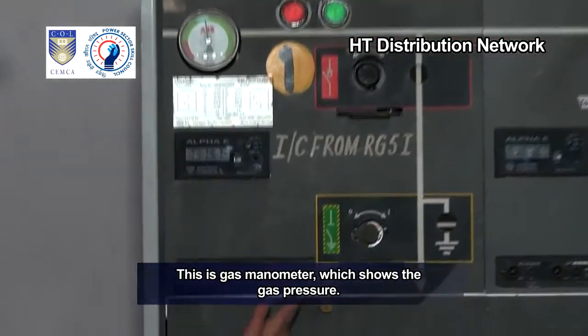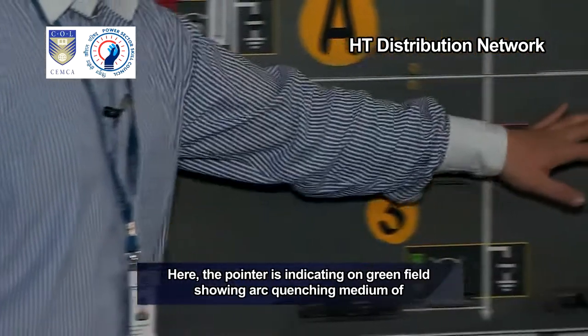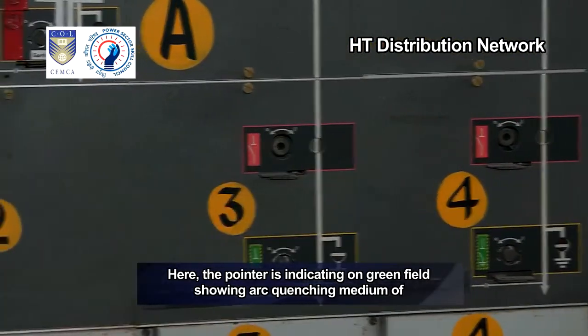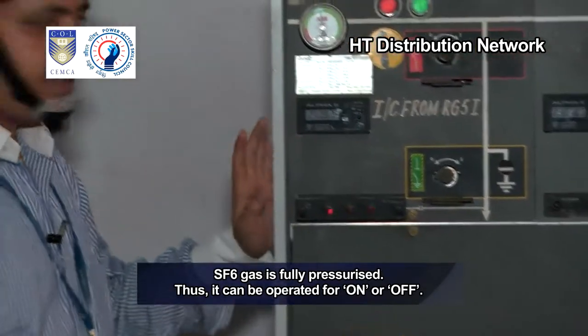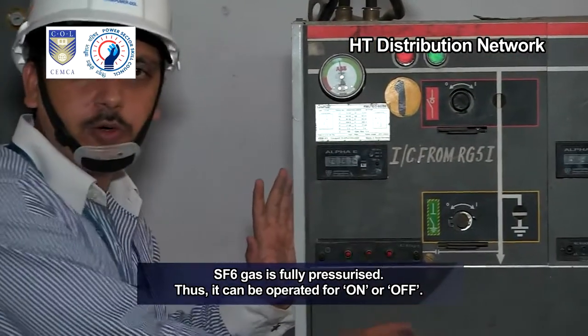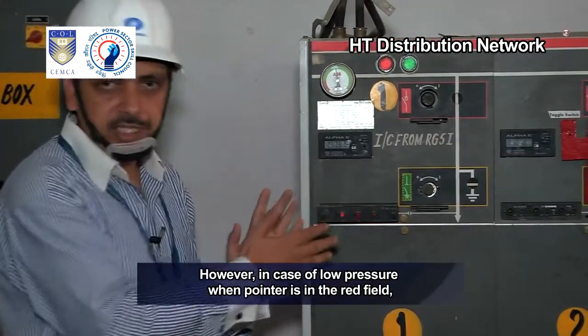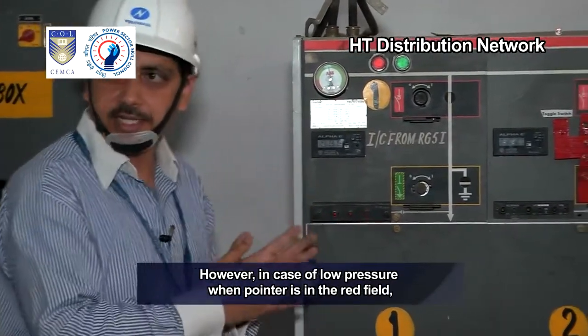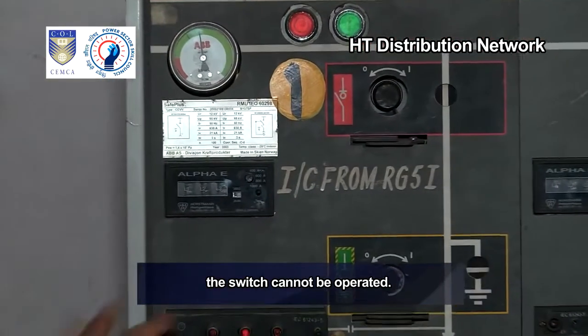This is the gas manometer which shows the gas pressure. Here the pointer is indicating on the green field, showing the arc quenching medium of SF6 gas is fully pressurized. Thus, it can be operated for on or off. However, in case of low pressure, when the pointer is in the red field, the switch cannot be operated.